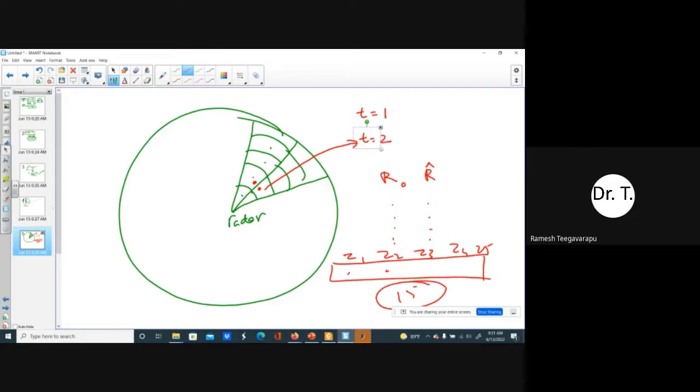So you'll have reflectivity, no reflectivity, and reflectivity. So in that case, we have to calculate the rainfall intensity in each of these individual time intervals, convert them into depths, and then add them to get the 15-minute depths. Once we have that, then we can compare the rain gauge versus radar precipitation.